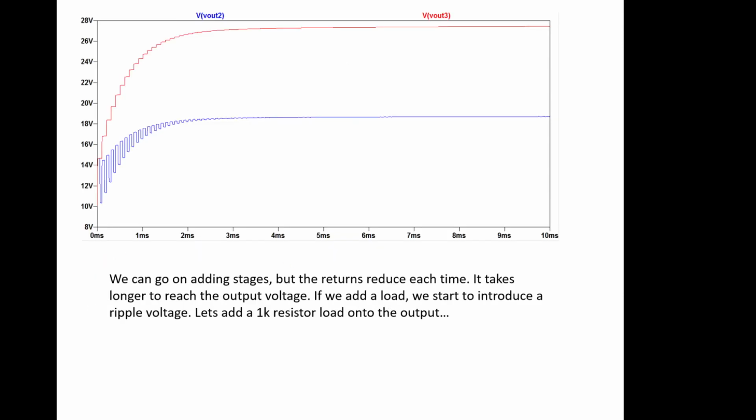So you can see, and here we are, the one is getting itself to 18 volts or 19 volts or so, and the other one is ramping itself up to, well, we're close to another 10 volts on top of that, so getting close to 30. If those diodes were ideal, we would be getting 30 out. So we've gone 10, 20, 30 in 3 stages.